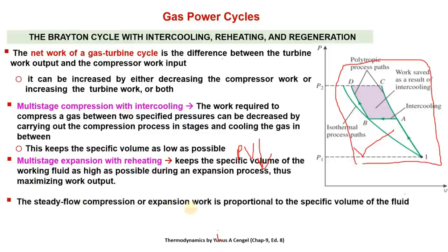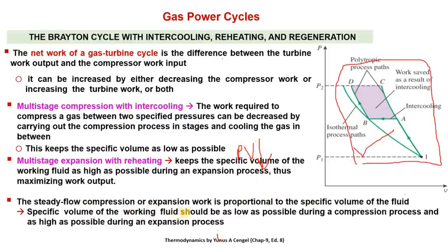So the steady flow compression or expansion work is proportional to the specific volume of the fluid. So specific volume of the working fluid should be as low as possible during compression process, and it should be as high as possible during an expansion process.